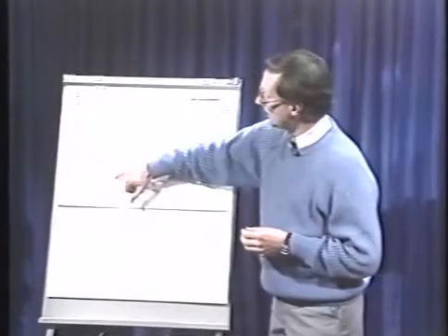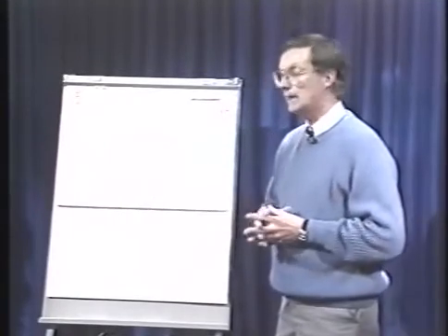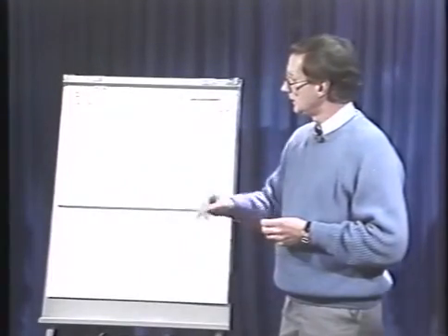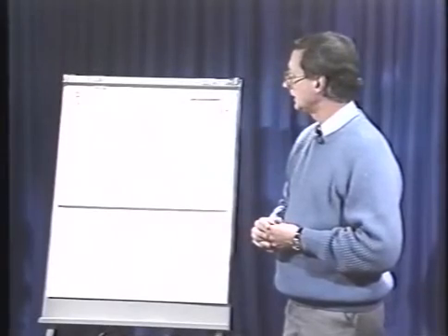It's inside this wire feed range of 70 to 420 IPM that we draw in current around 50, 60 amps to around 200 amps. This amperage range is the range for short circuit welding.